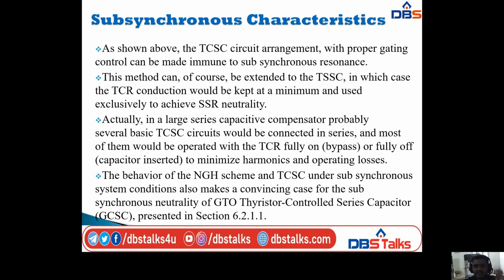So actually in a large series capacitor compensator, probably several basic TCSC circuits would be connected in series and most of them would be operated with the TCR fully on or fully off to minimize the harmonics and operating losses. So the behavior of NGHSP and TCSC under subsynchronous system conditions also make a convincing case for the subsynchronous neutrality of the GTO thyristor controlled series capacitor, that is GCSC, presented in the previous concept.